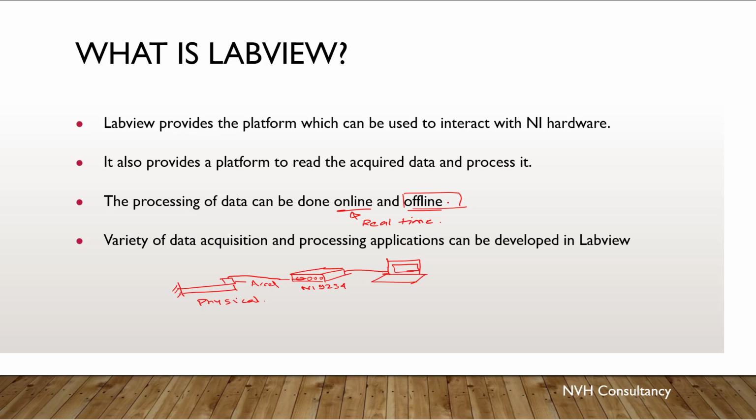kind of data processing. Sometimes in some applications you definitely need to go back and look at the data and process it offline and then create a different kind of module. Or sometimes you definitely need to process the data in real time. Suppose you are testing a bearing for a long duration of time, then real-time data processing can be very helpful, because you can set limits for the amount of vibrations that are induced at certain frequencies, and if it goes beyond that, real-time data processing will be very helpful,